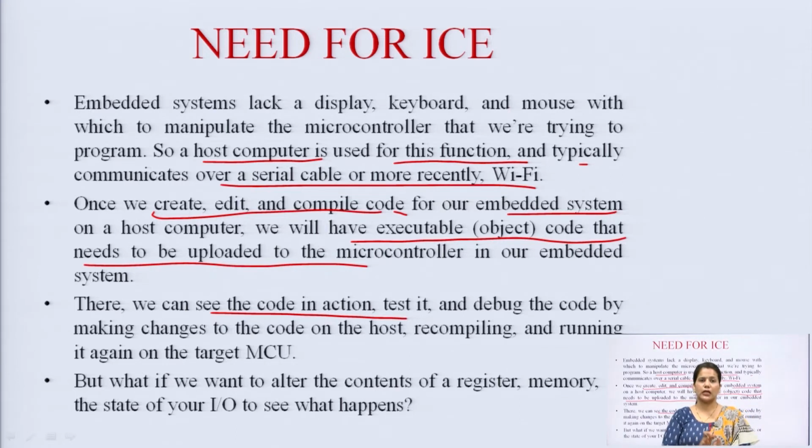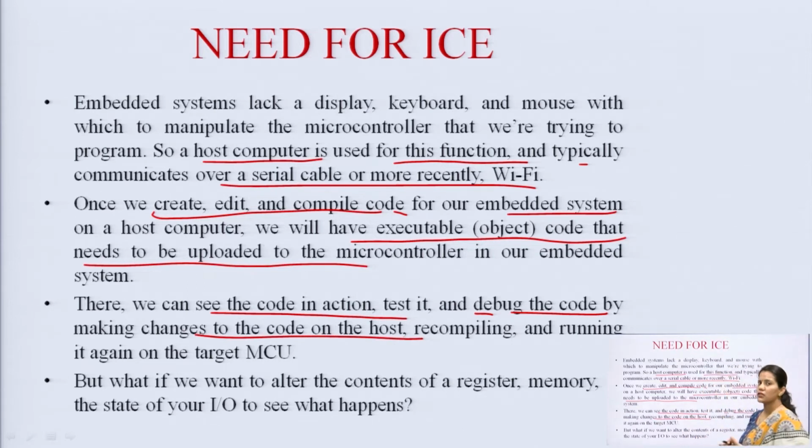Now, we can test whether the code that we have designed is working properly according to the application or not. It can be debugged again by making changes to the code on the host. Then we can upload it again and test on the target device. In this way the host computer is used again and again to check the software, debug it, make the changes, and upload it again. So, in this way we need a host computer for that purpose.